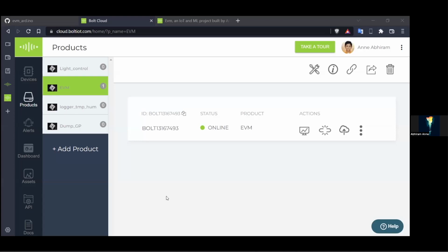So when you use that word, it will employ the internal resistance as a pull-up resistor. So now the Arduino module will know if you have pressed the switch or not. If you press the switch, it means logical 0. That means it is in low condition. If you release the switch, it is in high condition.